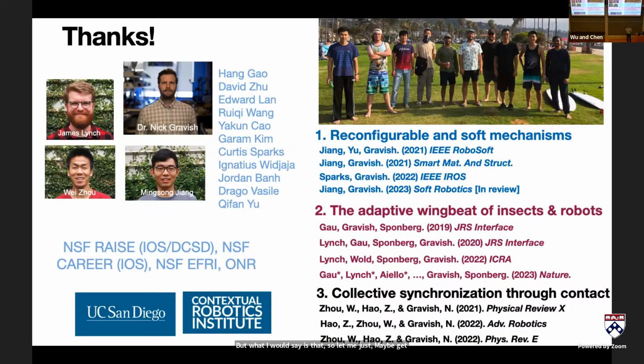The system that I showed with the worms is rigid links with a Dynamixel motor. We're doing as best we can to do proprioceptive sensing out of this Dynamixel motor. But if anybody's tried that with a cheap Dynamixel motor, you're definitely not measuring torque out of that thing, and at best you're tracking some variation in position. So what we're doing is watching position, and then converting that into a phase of the oscillator.